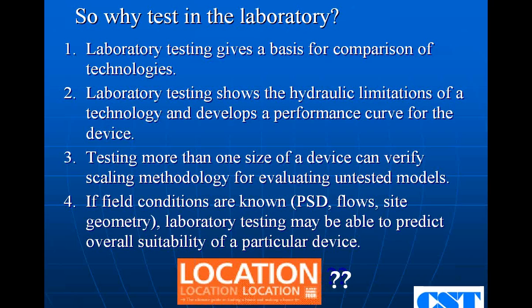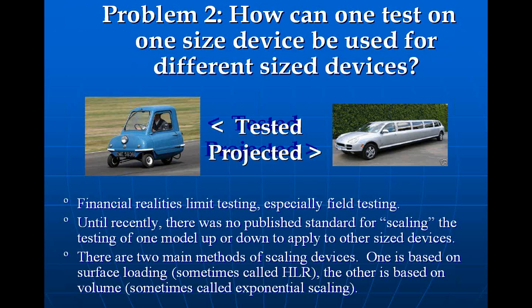First of all, the site isn't built. And secondly, if it is built and we're doing a retrofit, it's very unlikely someone has collected 15 storms or so to see what the particle size definition is. But if you got a good idea from similar sites, and you know the flow, and you know the site geometry, the slope of the gutters, the pipes, you may be able to use laboratory testing to get pretty close to a good suitability of a device on a site. So laboratory testing is certainly valuable.